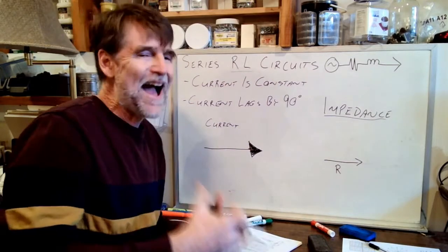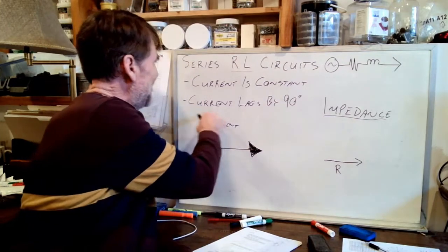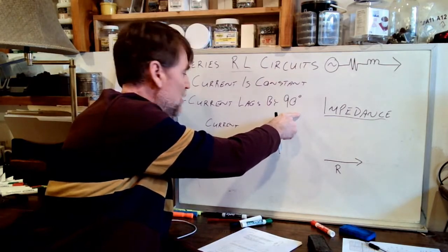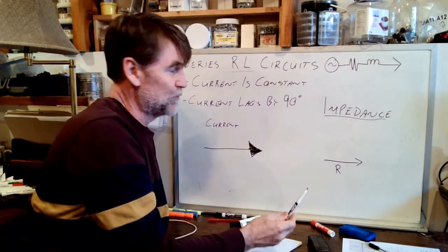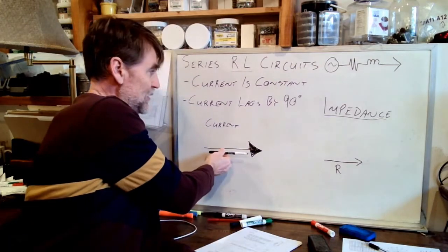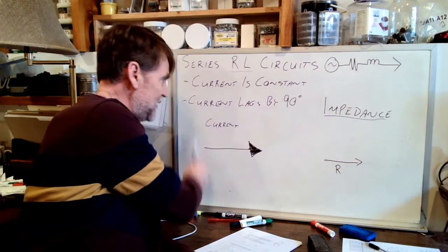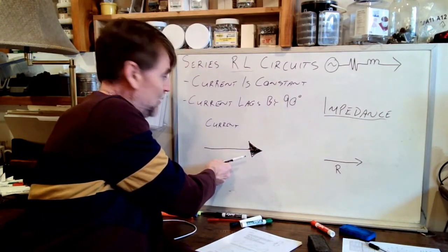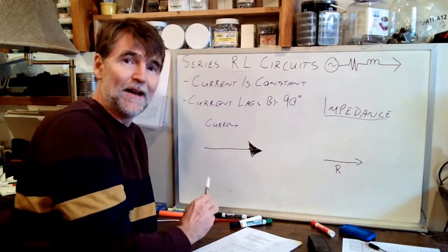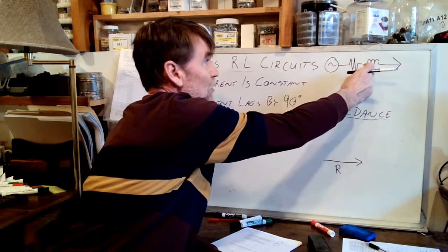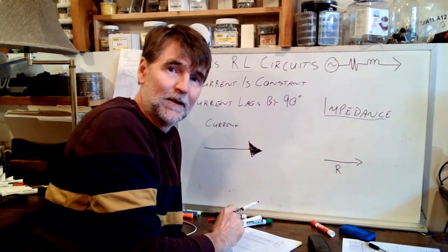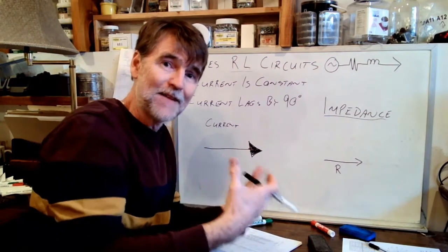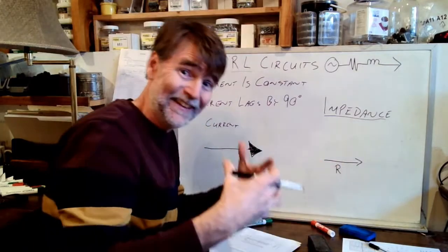The reactance in our circuit works at this theoretical 90-degree phase shift angle. We talked about the voltage vector. We drew the voltage vector at 90 degrees to our current vector, which is our reference. We've left this here because we're always referring everything back to it. If the voltage leads the current by 90 degrees, so we found the voltage vector at 90 degrees, then the reactance of that inductor influences the circuit linearly in that direction.